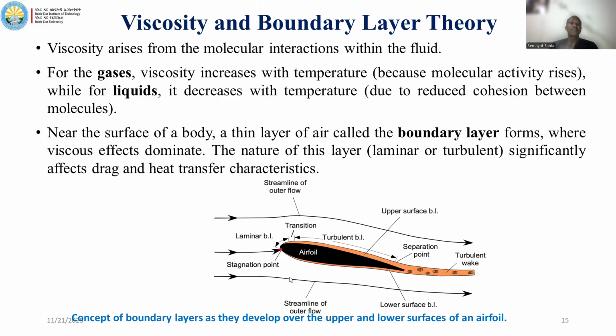Viscosity arises from molecular interaction within the fluid. For a gas, viscosity increases with temperature because of rising molecular activity, while for a liquid, it decreases with temperature due to reduction in cohesion between molecules.